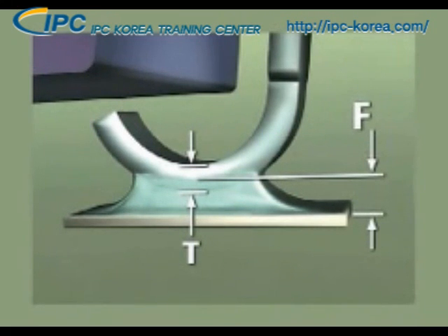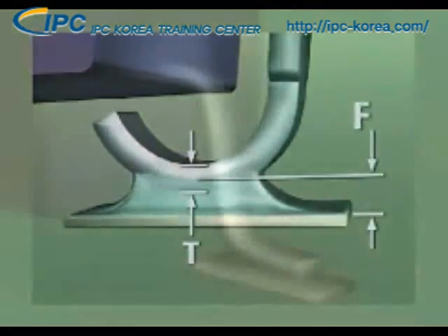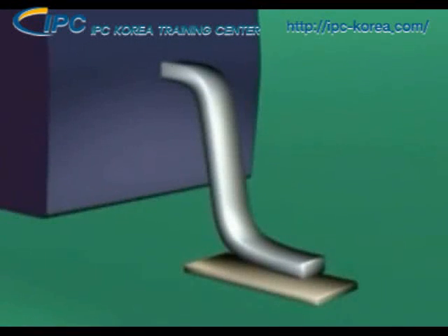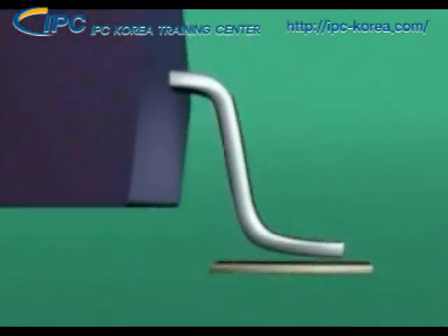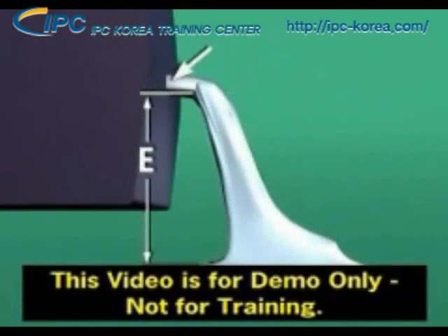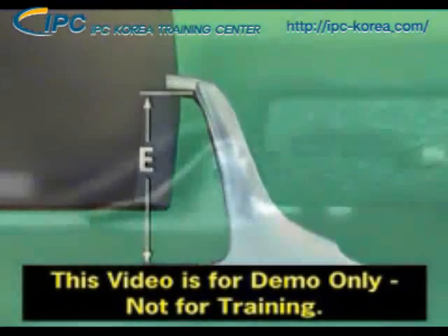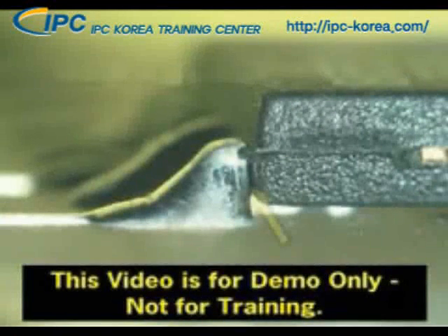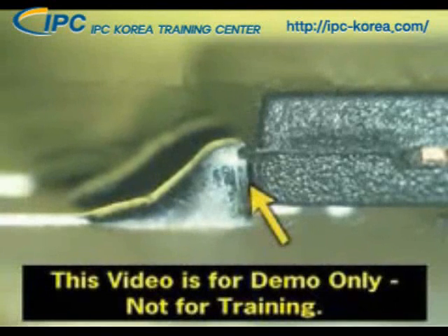Dimension T. For gull wings, the fillet height may extend to the top bend of the lead or knee, but should not touch the component body or end seal as a maximum fillet height. As an exception to this rule, solder may touch the body of plastic SOIC or SOT components.